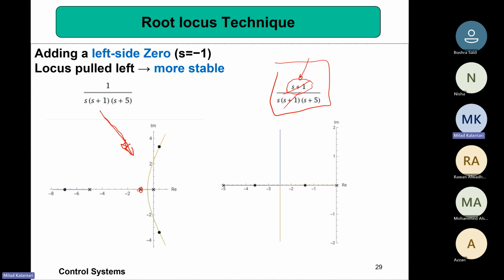So again, you can do the same way to figure out where the root locus is. This region is root locus because on the right side there is only one, an odd number. And also this region is root locus, right? Because there are three of them: one zero, one pole, and two poles, basically. So that whole location can be basically root locus, right?